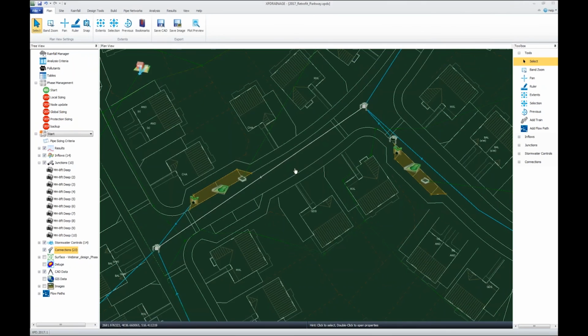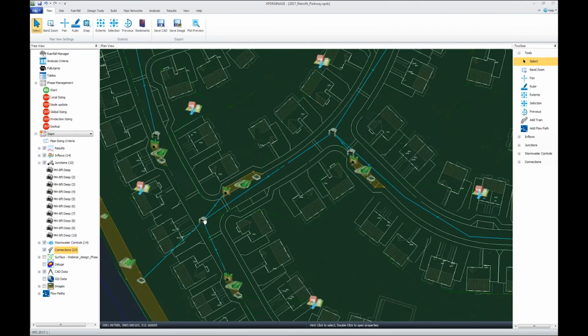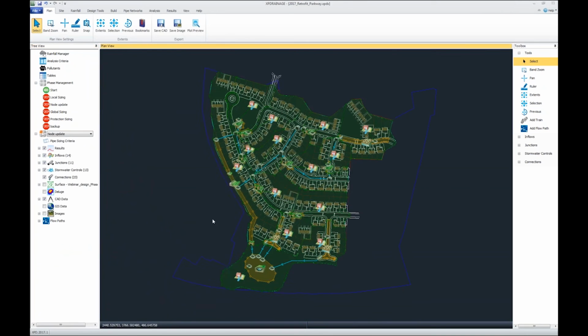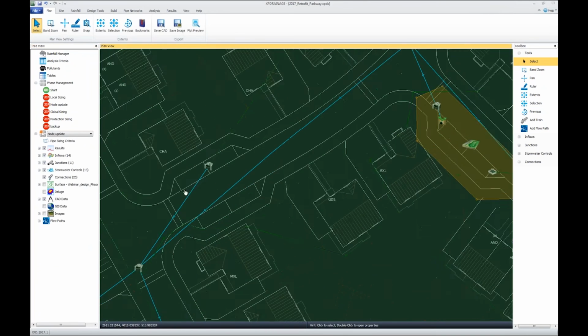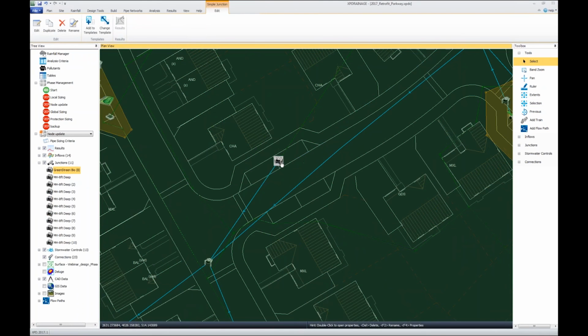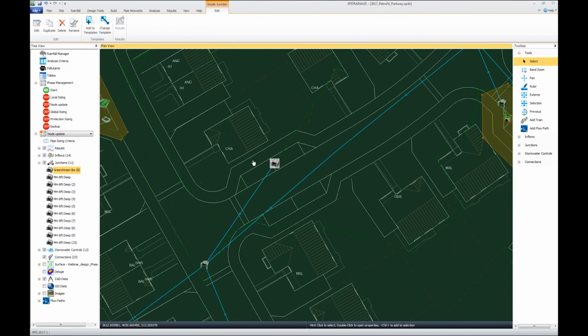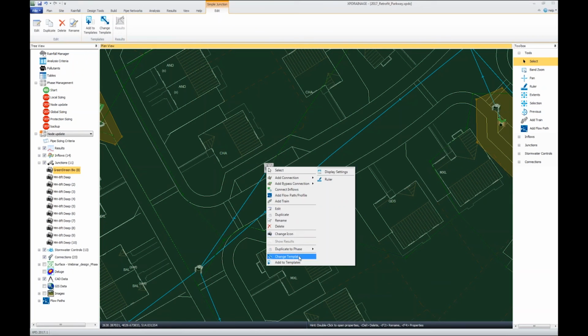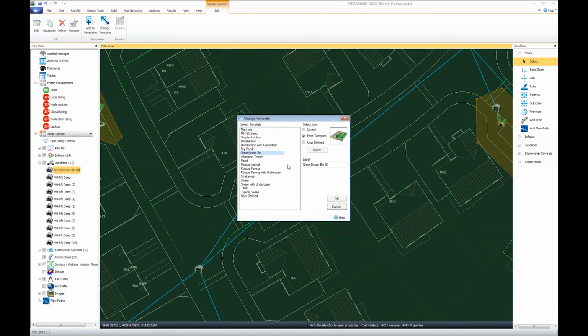Now, the issue, of course, if you import just a pipe network into the software, is that the idea of these ponds doesn't exist. They're just a point. So I happen to have changed part of the software. If we imported this item directly from LandXML from scratch, we're automatically associating names with XPDRAINAGE objects. If you just started a model from scratch, you might have, let's say, a manhole that needs to be a pond, or needs to be something else. Well, it's as easy as changing a template. I can change this to be a rain garden.